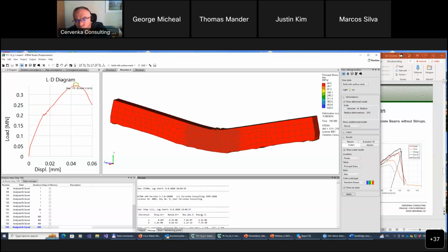And this will show itself in the analysis: the analysis will keep running, the displacements will always be increasing, and convergence cannot be reached. So if I were loading by forces, I would have to use the arc-length method to go to post-peak. But in this analysis, I am using displacement control, prescribing displacement, so I can use the Newton-Raphson method, and I can calculate post-peak without using the arc-length method. So now I'm in the post-peak. Nicely, you can see the deformed shape. Somehow it seems like there may be even some shear crack.